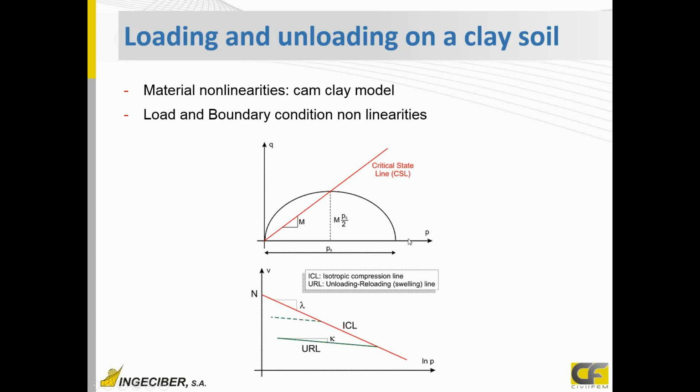For this model, it's very important to define this plastic yielding surface. The way to do that is by defining the consolidation pressure that my model had previously. In that way, the software defines this over consolidation stress. If I'm moving outside this, I will have this relationship between volumes and pressure, that is, I will go through this red line.